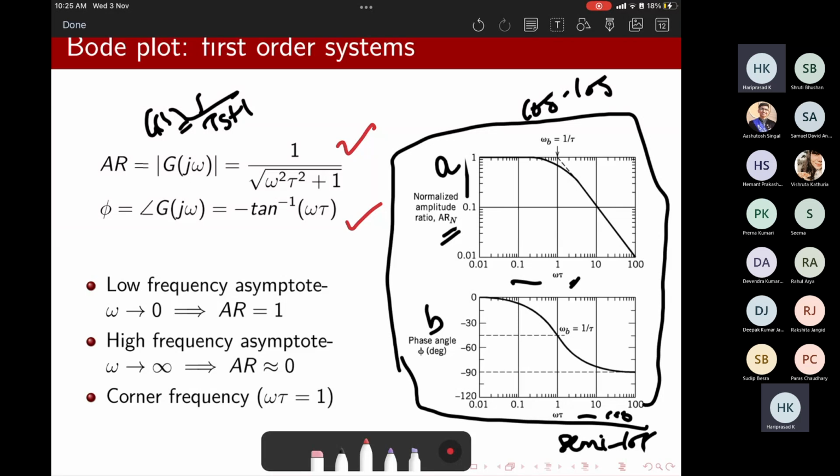Why do you need a semi-log plot? Because you have to represent all potential values of omega. So these potential values could vary from how much? From 0 to a very large number, right? Maybe 100,000, just to make sure that whenever we are going close to the high end, because we are now looking at the perturbation of the system for various frequencies. Various frequencies essentially means that there will be no frequency and there is very high frequency. So both extremes you should be able to cover.